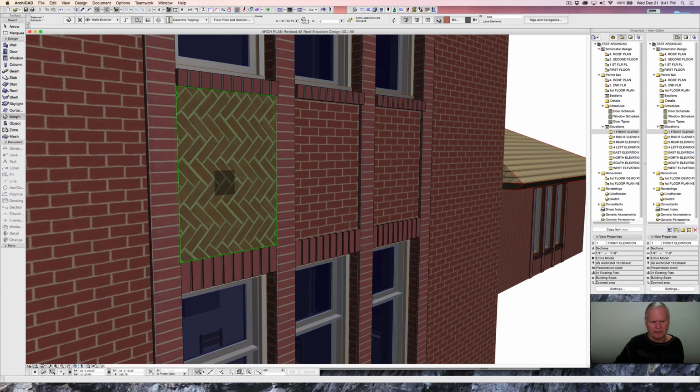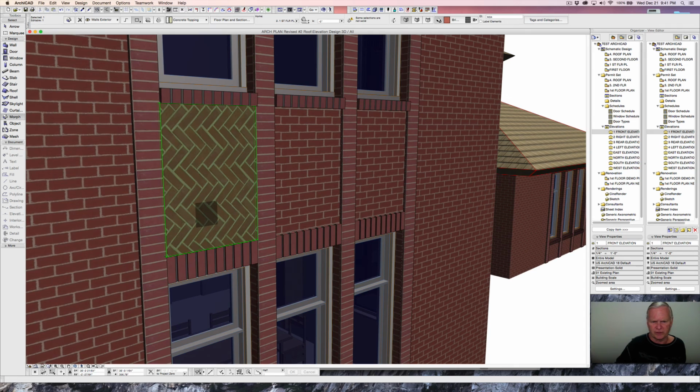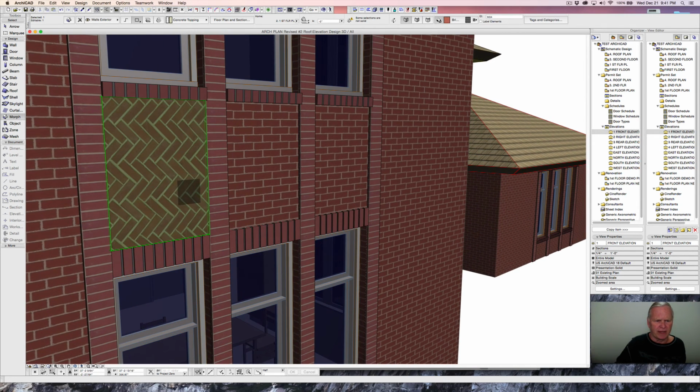And then we won't get that because it's just a surface. That was just a skin there. When we get different views of it, it just flutters like that. And so you have to give it some kind of thickness. You know, I find an inch works. It could be a half inch. And now I've got this.